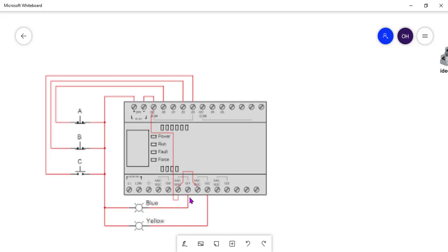You got it now? The outputs of the PLC are negative, because the positive is also coming this way to complete it. So when I switch, this output cannot come on until the program is executed. You get that? Okay. So it is this program that powers these outputs that is our business: to write this program, condition them, and load them, so that when we make any input, our output will be energized in accordance with our instruction.